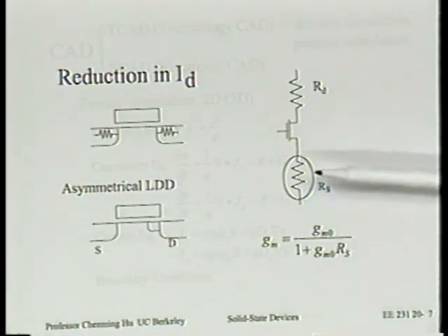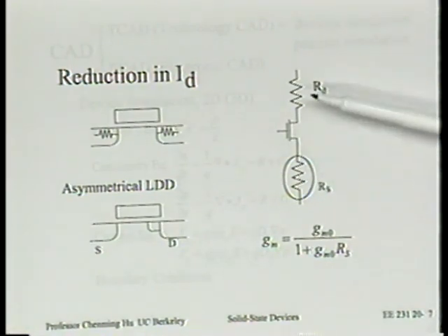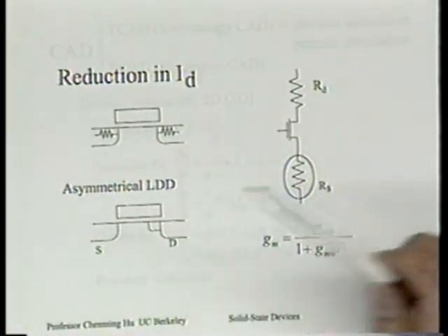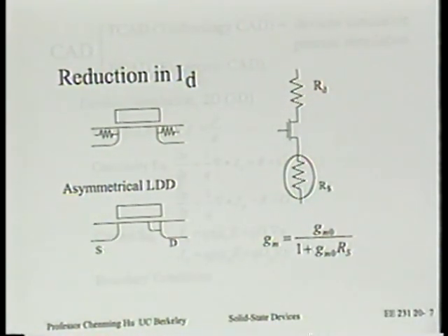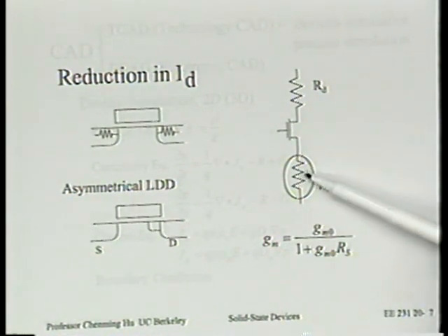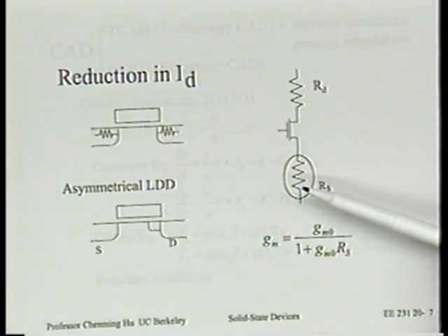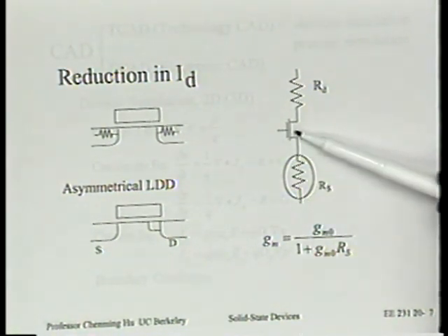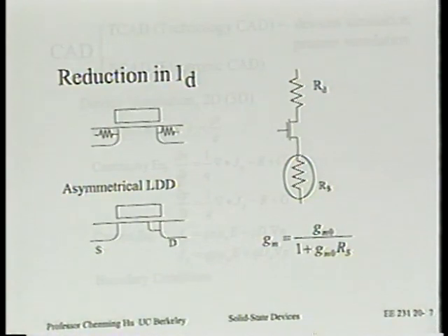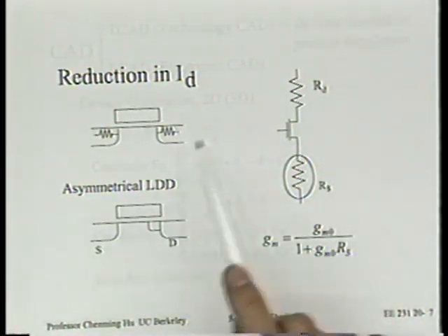It will certainly be hurt by the presence of these extra resistances introduced by LDD. Is that right? Okay. Now do you remember between these two resistances, which is the more serious problem for the performance of the transistor? Is it RS or RD, or are they equally problematic? RS, because RS causes reduction in internal VGS, and that's why it causes reduction in the current, right? And RD only pushes the VDSAT out more.